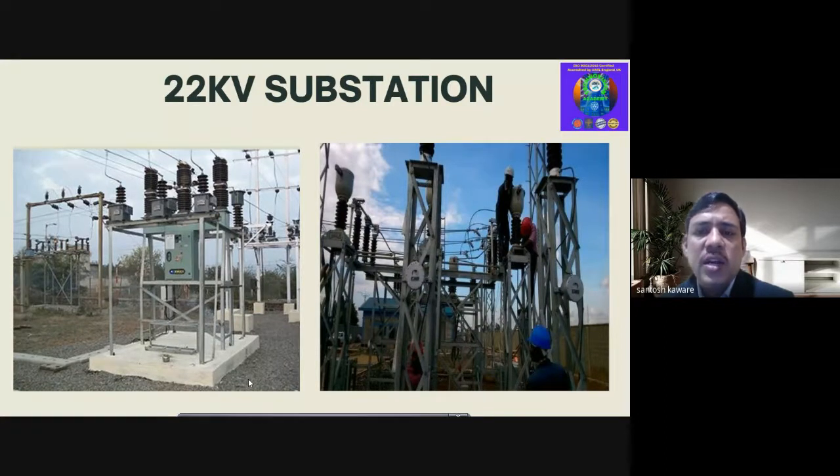Again at site, whenever you fix that equipment, you test it by your measuring methods as per your standards, at your substation or industry. Even for certain contracts, the company representative may come to the site during your testing. That is the site acceptance test.